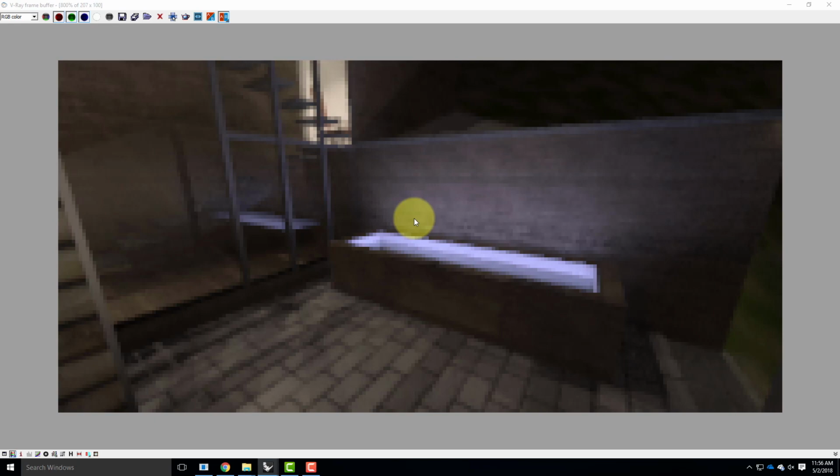I did run a group of 3D prints this morning. So a few of you have 3D prints. There's a couple more still running on the machines. Out of all the uploads for assignment 203, I had 10 people include object files of however many you are. So that wasn't too many. Furthermore, of the 10 that did include object files, only 6 of them actually worked. So it shows you how the odds kind of play out. So I'll come around and I'll talk to you if yours didn't work. Generally speaking, the ones that didn't work were because the object was too far away from the origin, and you had to take that object and move it closer to the origin in order to run it.